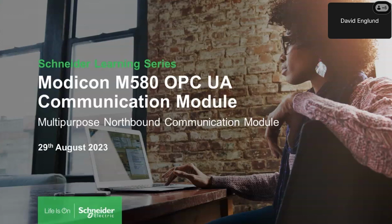That's because we were showing it as a PLC to PLC use case, but you could absolutely use this to read from a PC-based UA server, a Linux-based OPC UA server, or even some HMIs, like our operator terminal expert HMIs, which can be OPC servers.